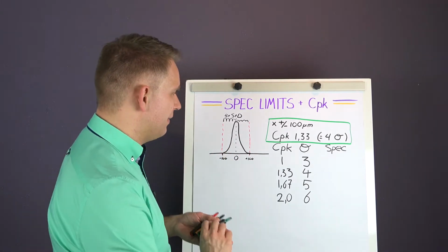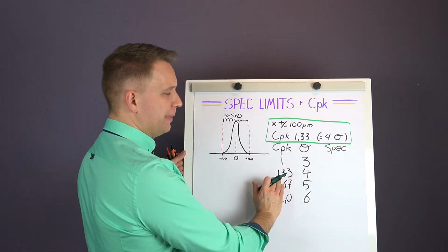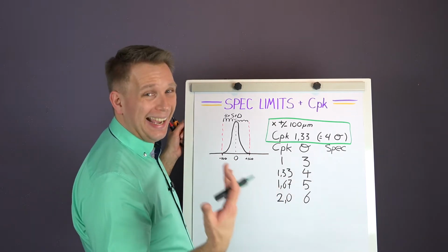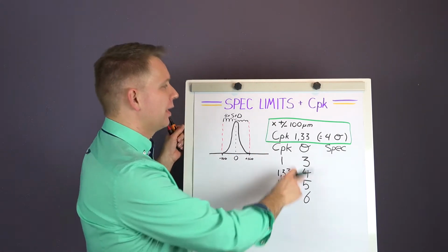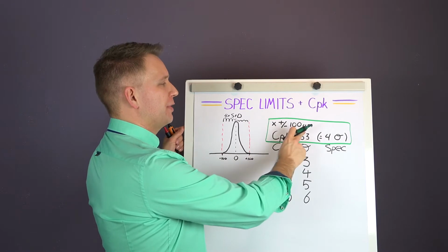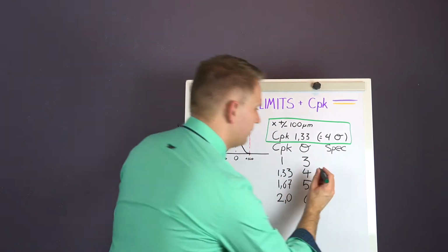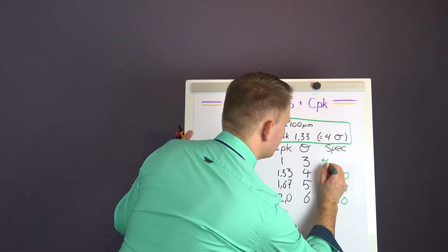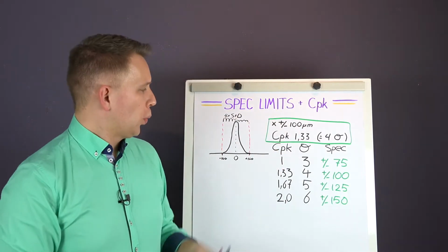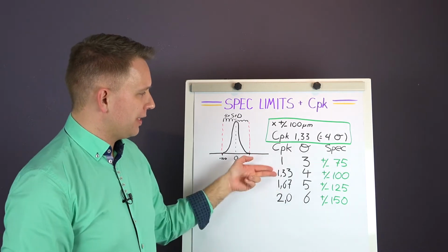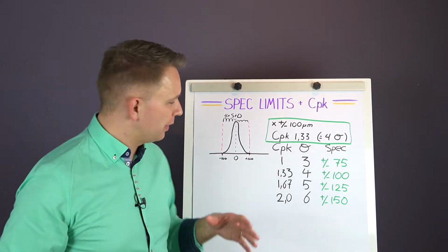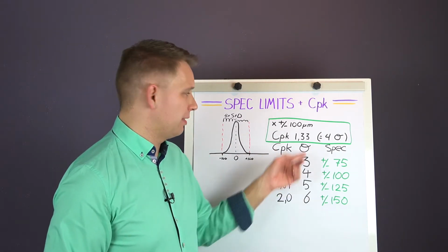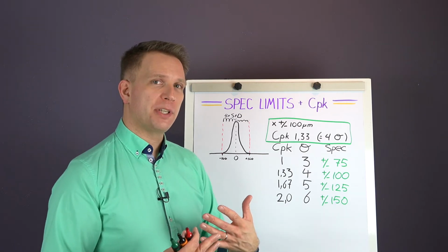In the table, what is given is for the CPK of 1.33 and a sigma of 4. This we get in our product when there is a specification tolerance of plus minus 100. Now, what they say is, if this is our process, an equivalent of that, so if we really want a CPK of 2, we should have 6 standard deviations between our specification limits.